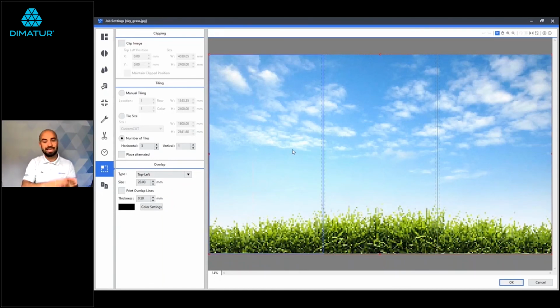You can lay either end first when it comes to applying. So I could start with my left-hand tile, or I could start with my right-hand tile, because there will always be an overlap available to go either on top of or on the other tile. The preference is normally down to where it's being put up within a room. If I was putting this into a room and the entrance was on the right-hand side, this normally means that you would start on the left-hand side, so the overlap join is not visible when you walk into the room.